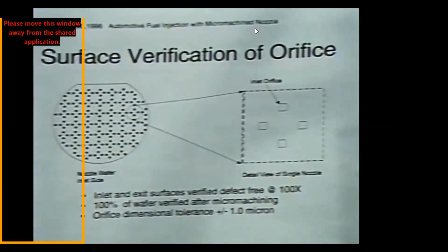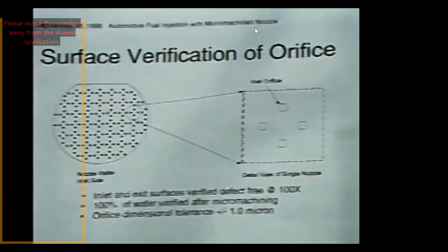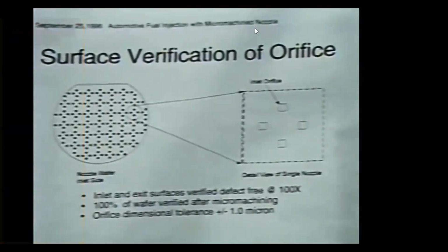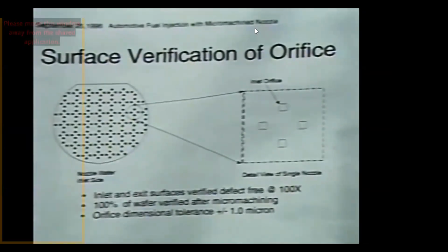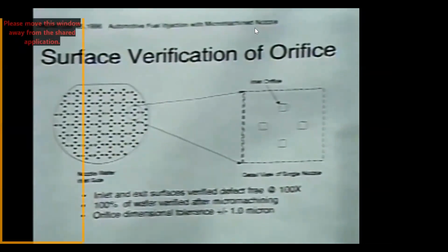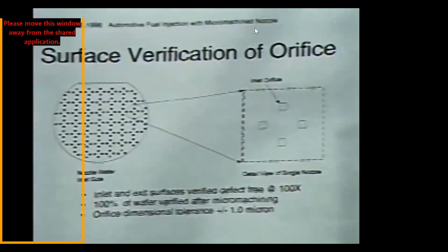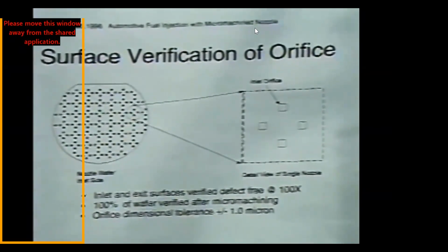After the surface inspection, we would go in and inspect every single orifice. We had a very high magnification inspection system, and we would inspect the size of each one of the orifices. These sizes were then converted into a dimension that we would graph out regularly and control on our system. If something was too large or too small, it would be put onto a wafer map and later rejected in our pick and place operation.